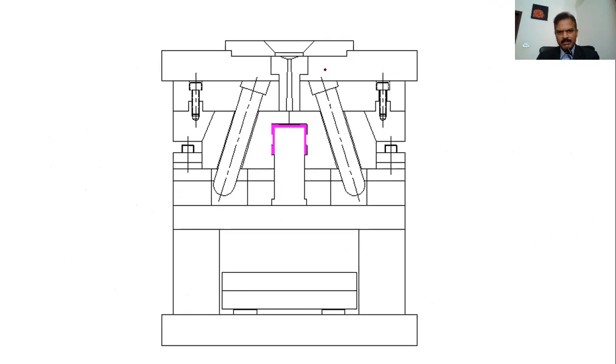See the finger mounted at 15 degrees, and the wedge. So the angle of the wedge is 5 degrees more. So that means it's 20 degrees. Now we have cleared the core and the core plate in this case, so that the finger will not interfere with the lump of steel there. And what you see here is the keeper plate, this line, this thickness here, and this is the thickness of the channel.